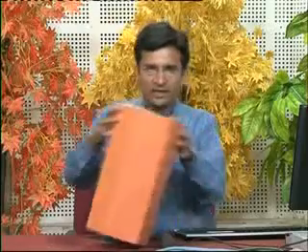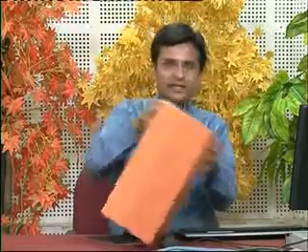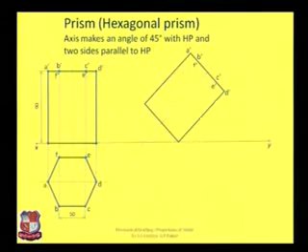So tilt this solid. First is this, the second is this one. By tilting this, here we have tilted its front view like this. After tilting, to draw its top view, let me take projections from each point. So these are the lines. Now to draw projections, draw horizontal lines from top view.